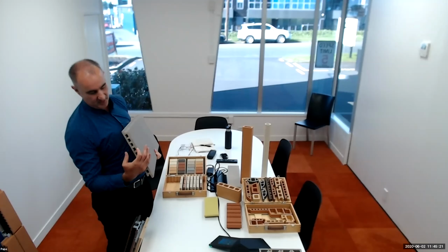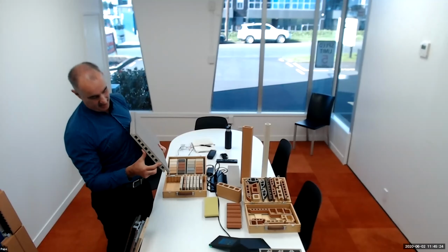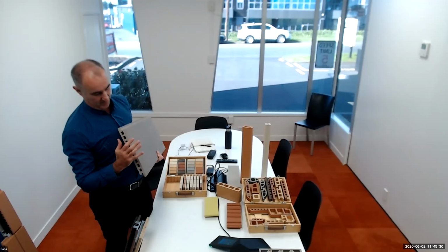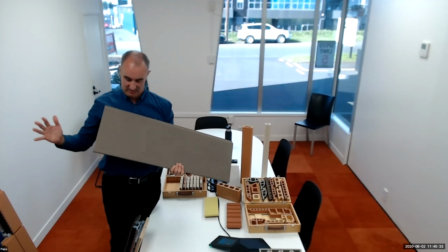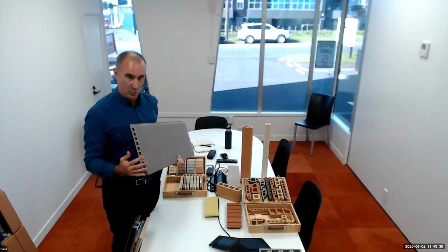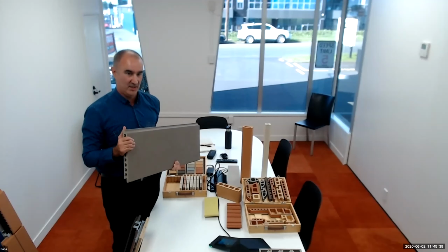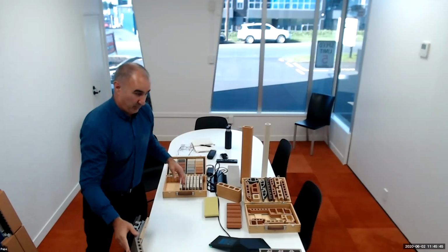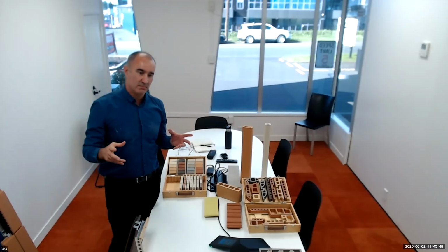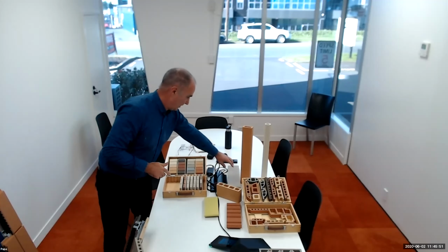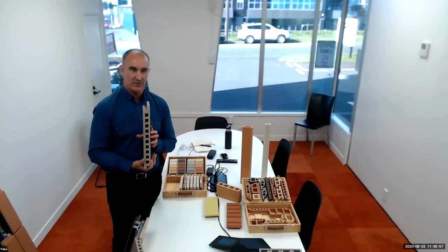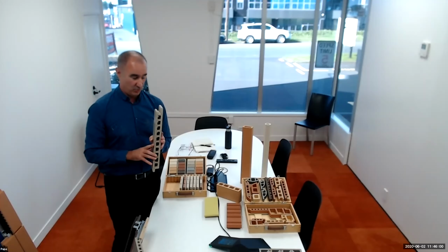But this is, as I said, a typical tile that we use, 30 mil thick, with a honeycombed sort of interior to help with strength. So it's a double skin. This particular thickness can go up to 1.8 meters by 500. That can be the size of your format. If you want to go bigger than that, we can go 3 meters by 800, which is the maximum tile size we can do. But you then go to a 40 millimeter thick tile. That does increase your weight, obviously, but it gives you a much larger format.